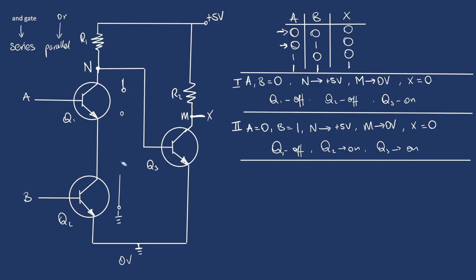Okay. So we raise this and work with a blank slate. Case 3. A is high and B is low. Okay? What does that mean for us? So now that A is high, this is 1 and this is 0. We know that no current enters Q2. This guy turns off. Some current enters here. This guy turns on. Alright?